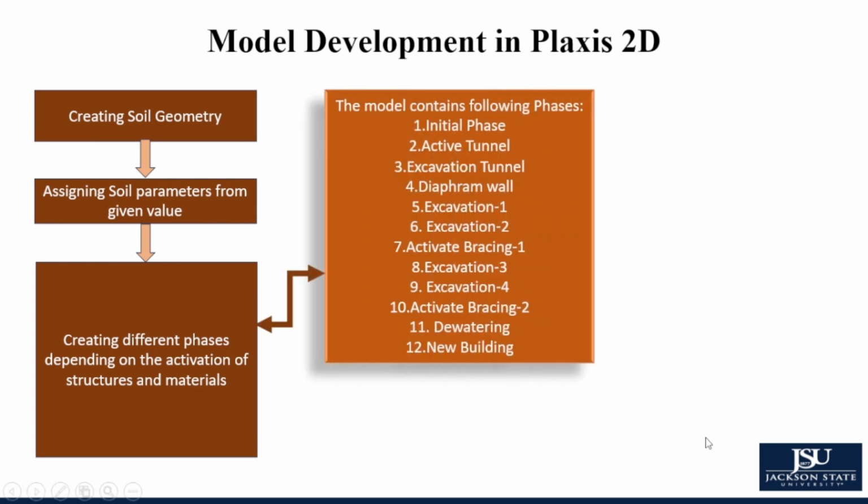Here are all the phases: initial phase, activate tunnel, excavation of tunnel, diaphragm wall, first two phases of excavation, then activating bracing, then second two phases of excavation, then activating bracing 2, then we did dewatering, and then the new building was built there.